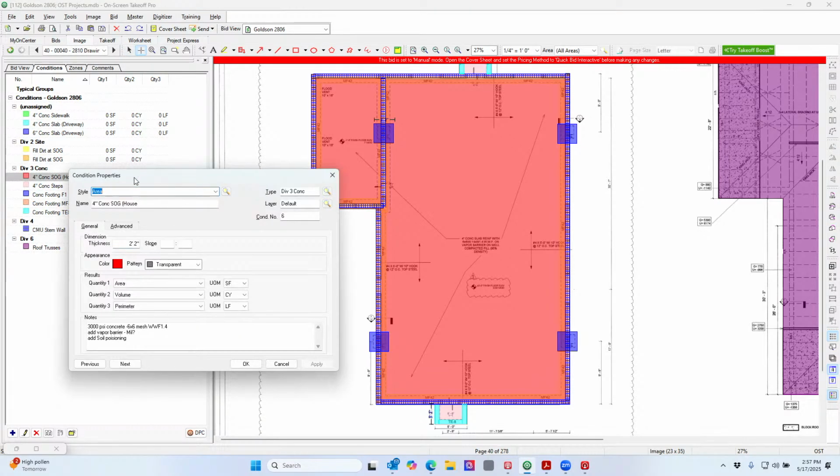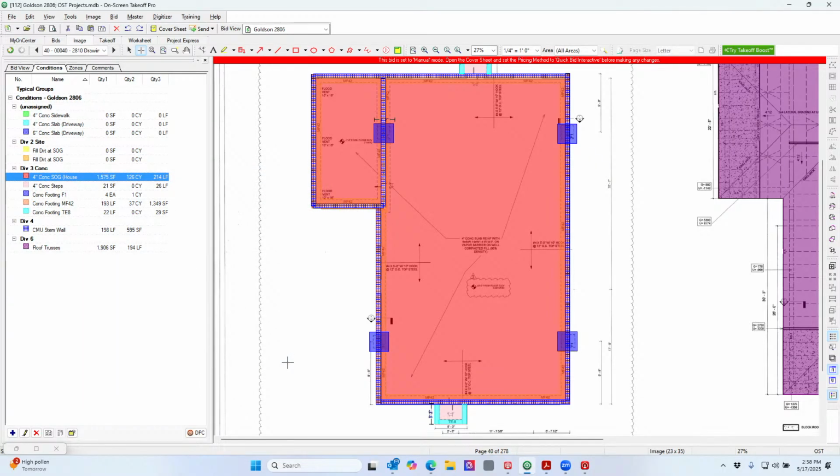Is there a calculation for accounting for compaction, or do you just add a certain amount? So you would add, depending on what, now you're getting into advanced estimating. I'm asking because I lost a lot of money on a stem wall. Honestly, compaction depends on the type of field you have. So you would have to get that information from the place where you're getting the dirt. Normally compaction can be 10 to 15%. So yeah, you would add a waste of 10 to 15% on here. It depends on what kind of sand you have, because all sand doesn't compact the same.